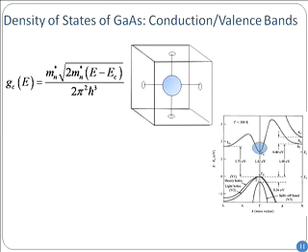Do you remember that for gallium arsenide, on the right hand side, I have shown the E-k diagram, and there are these two panels which have been pushed together. The panel being Gamma to X, which was one panel, and Gamma to L being another panel.